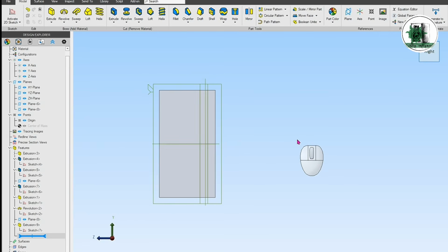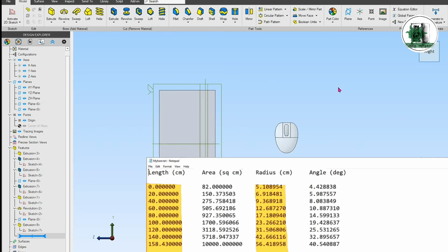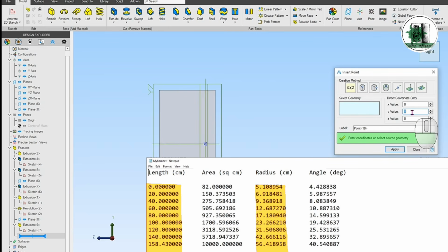The final step is to import the horn profile points into the CAD software. This is very simple. The radius and length values are all we need to create the horn profile. Multiply each point by 10 and enter them into the CAD software. For the first point, enter 55.5, the same value we used for the horn throat in the sketch. The value 26 for Z includes both the horn plate and the mounting depth of the driver frame.